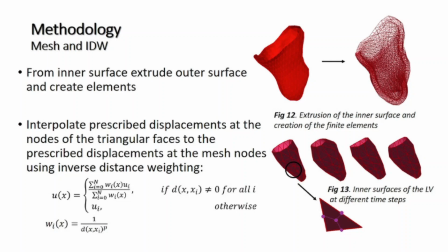Inverse distance weighting is a type of deterministic method for multivariate interpolation with a known scattered set of points. The values assigned to unknown points are calculated with a weighted average of the values available at the known points. The name given to this type of method was motivated by the weighted average applied, since it resorts to the inverse of the distance to each known point when assigning weights.